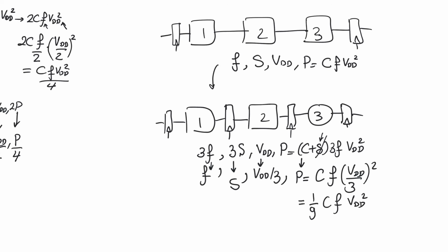So we're seeing the same quadratic improvement that we saw from parallelism, but with less cost because we are not multiplying the area. The area has not been doubled or tripled. We just have the area of the additional pipeline registers, which is much less significant than parallelizing the combinational logic blocks. But we have the same limitations that we had in parallelism.